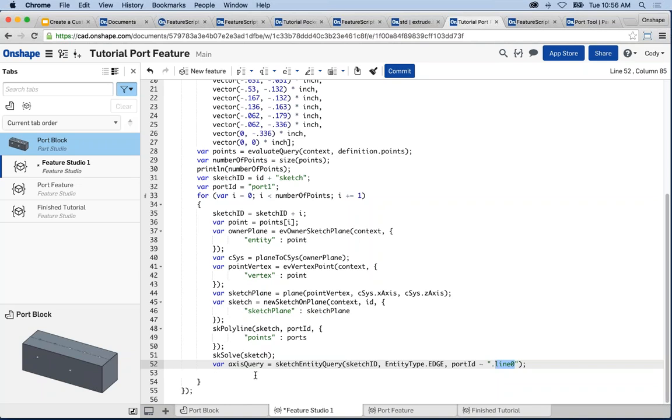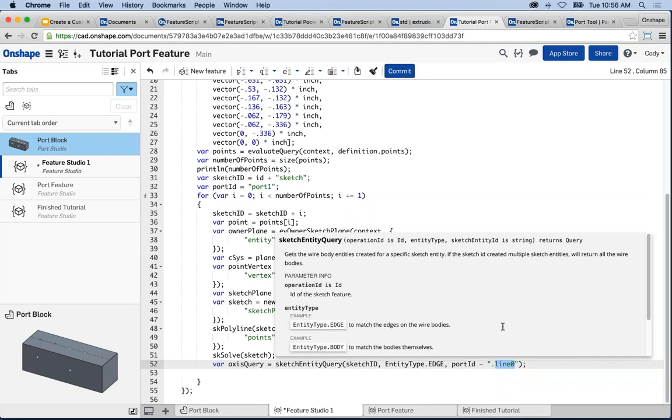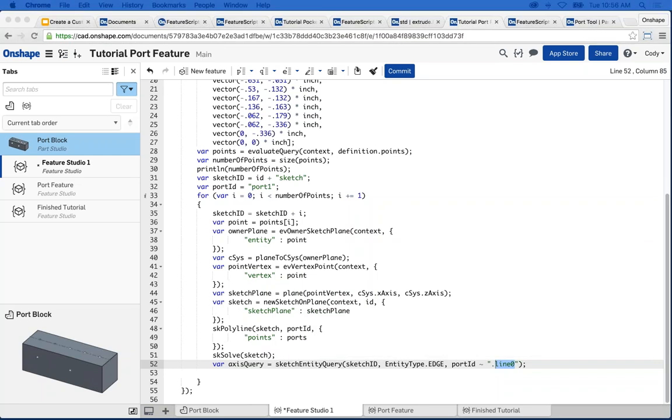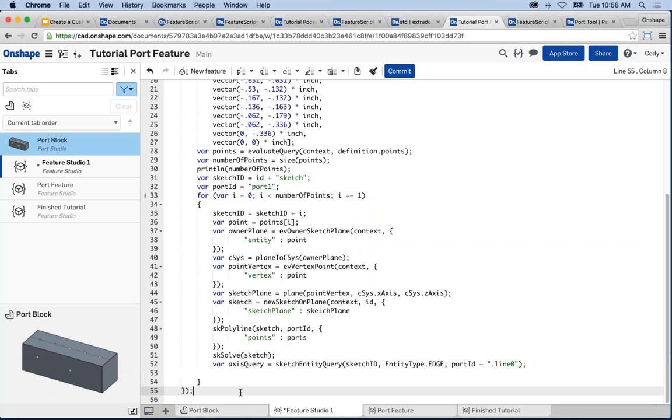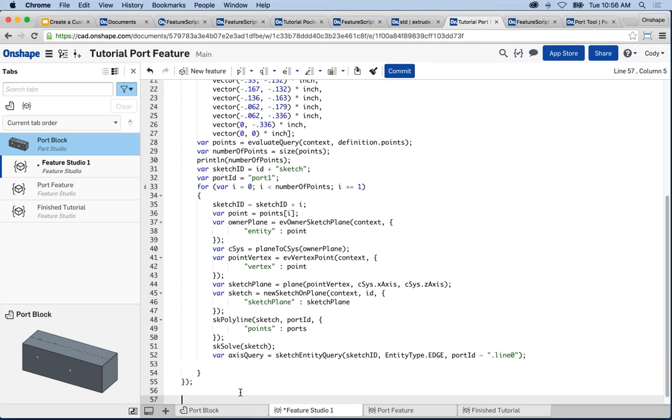The reason this is important is that as we create a revolve, we need to reference that line. Now, just tying back to some of the questions before, you can create separate functions within your feature script. So I want a separate function for the Revolve Cut. And just real quickly, if you're looking for the example of the code, check out the finished example.